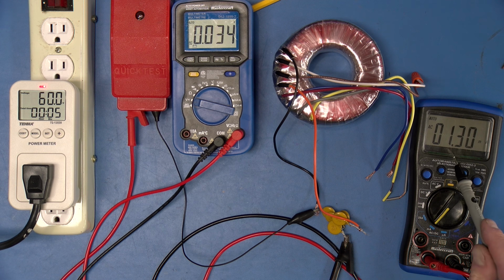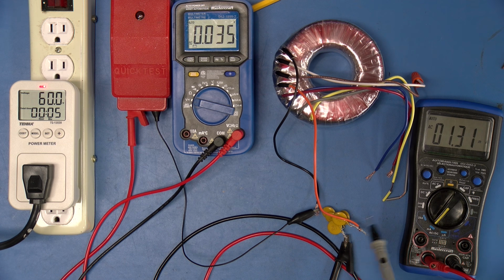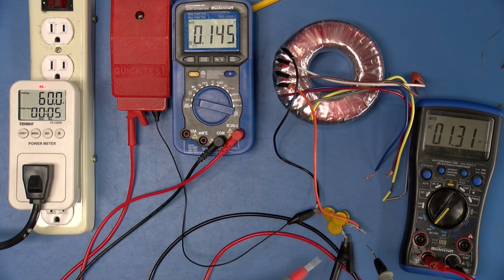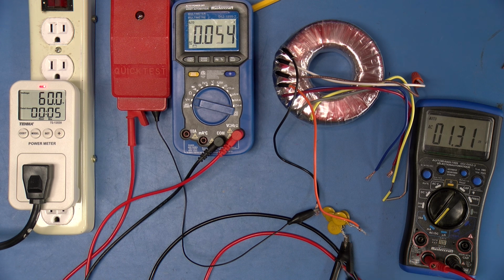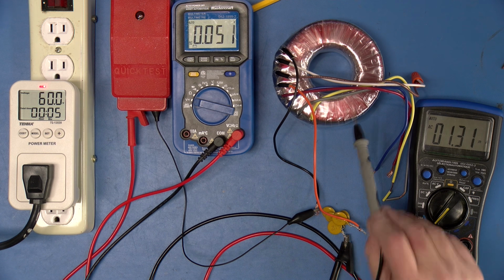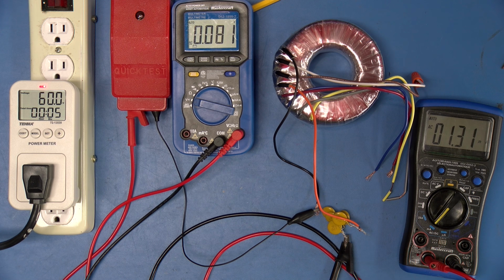And since the current is 1.3 milliamps and we know all the voltages, the total across the system, across the inductor, and across the capacitors, you could now, using phasors, calculate what the phase angles of the individual voltages across the capacitor and inductor actually are. So there you go, a real-world example of what we talked about.